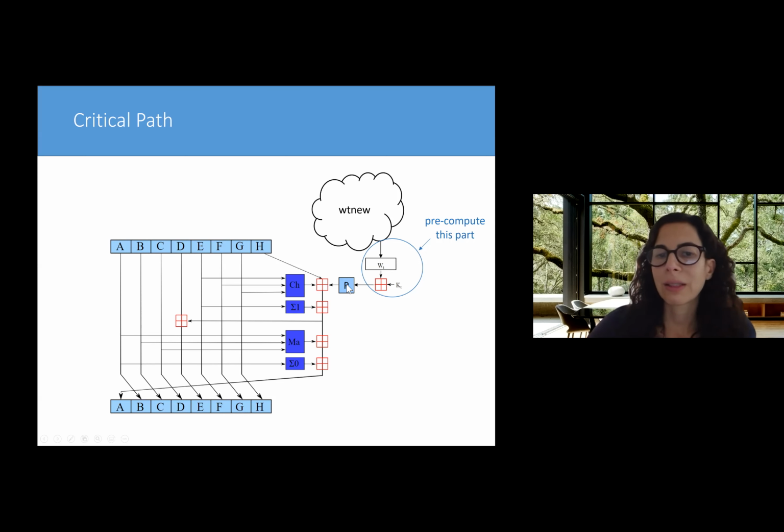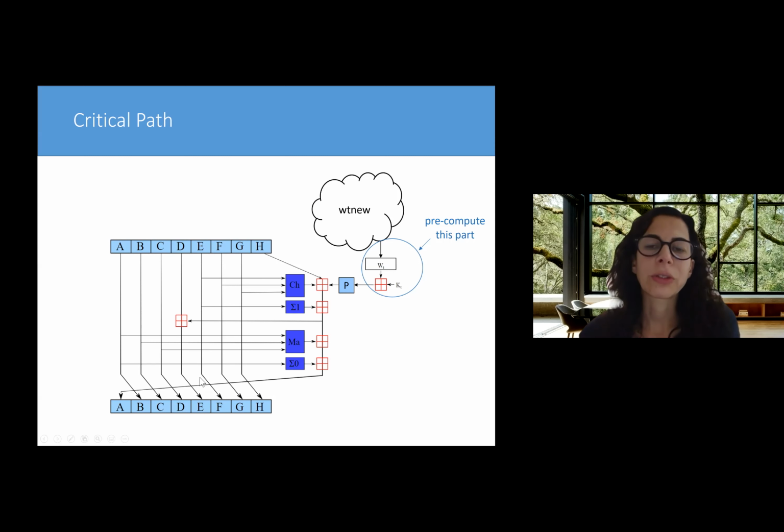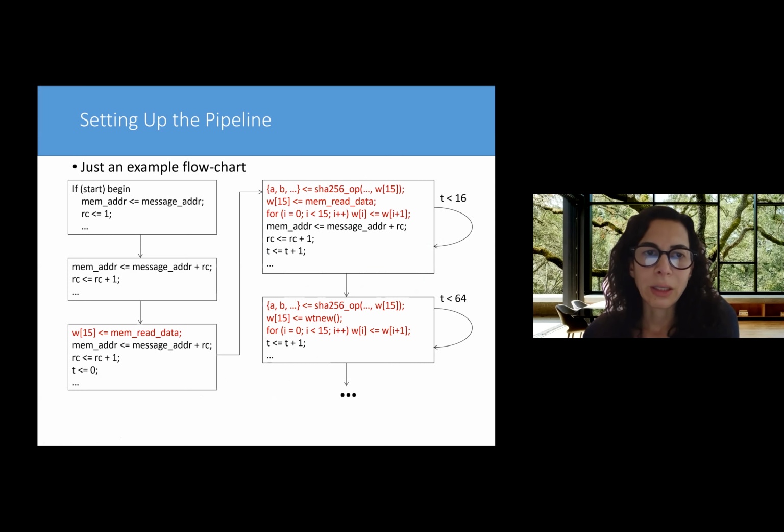Then this gets out of the critical path. Then the critical path only becomes the path that we are taking from here to here, all the way to the next registers. And that is going to help us have much better timing of the critical path. So now, that means we have to do some pipelining, and we have discussed pipelining.